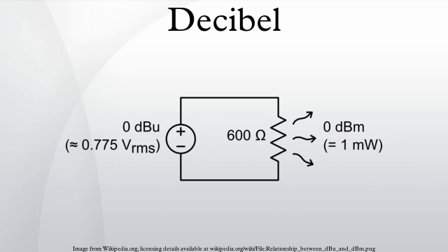Definition: the decibel is 1/10 of the bell, so 1 bel equals 10 decibels. The bel represents a ratio between two power quantities of 10:1, and a ratio between two field quantities of √10:1. A field quantity is a quantity such as voltage, current, pressure, electric field strength, velocity, or charge density, the square of which in linear systems is proportional to power.